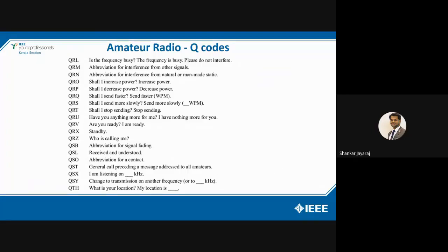So I will show how we properly communicate with amateur radio. It goes in this format: CQ, CQ, CQ. This is Victor Uniform Number 3, Foxtrot India Yankee. Anyone on the frequency, copy? This is the first dialogue I use while pressing the PTT button on the handy that VZR uses. I will repeat: CQ, CQ, CQ. It is a general call. That is the meaning of CQ, CQ, CQ.